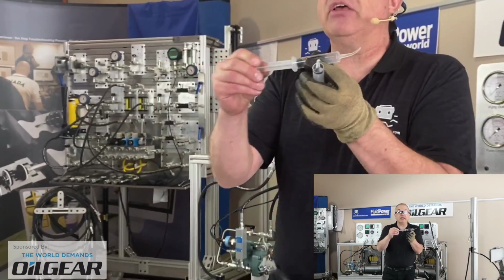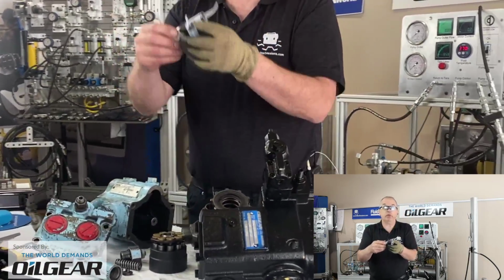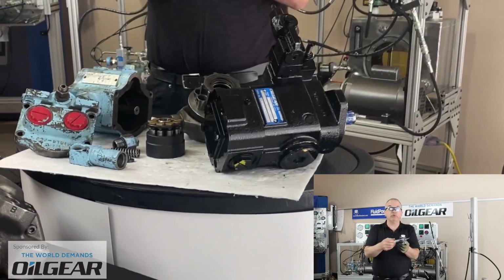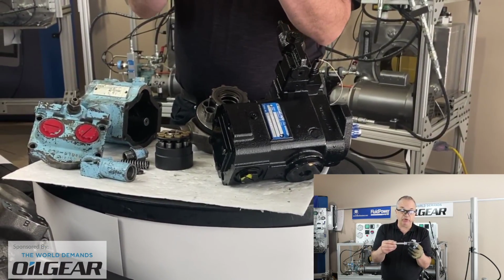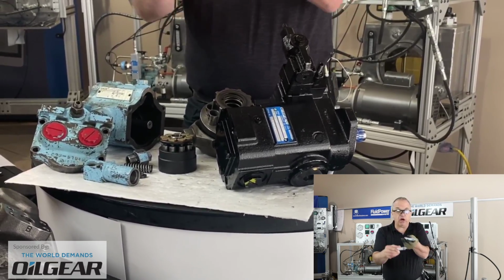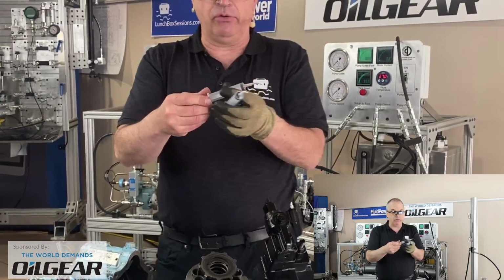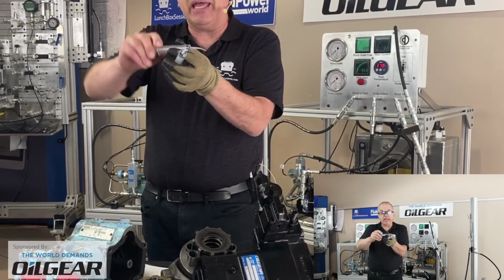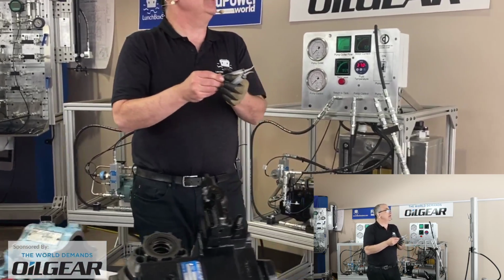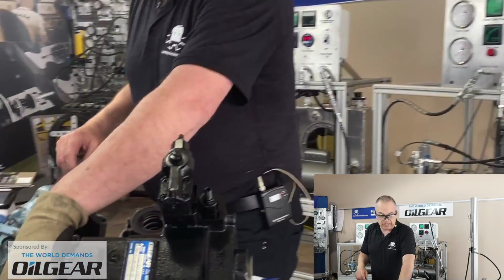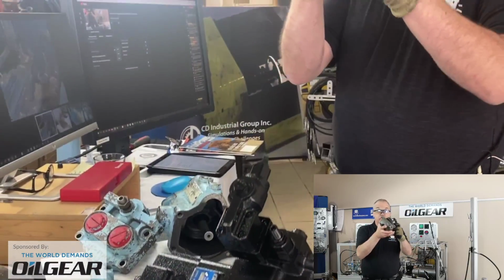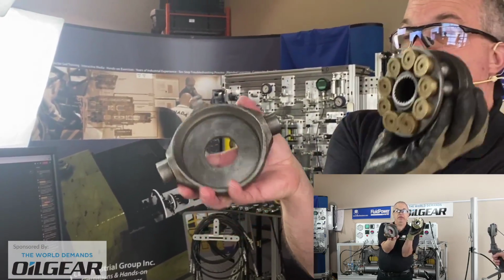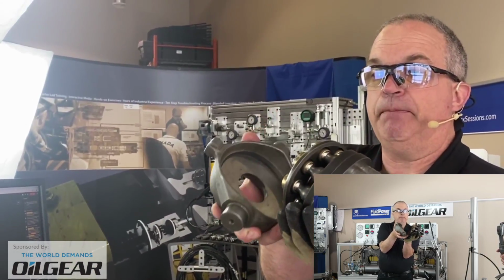What does a syringe like this have in common with a piston pump? It's a very similar concept. In fact, you may have seen some of our 3D videos where piston pumps are likened to a group of these syringes spinning around on an axis and sucking in some fluid and then discharging again at a different point in the rotation. Some people like to call the axial piston pump a swash plate pump. There's the swash plate, and there's the piston slipper pads at the back there.